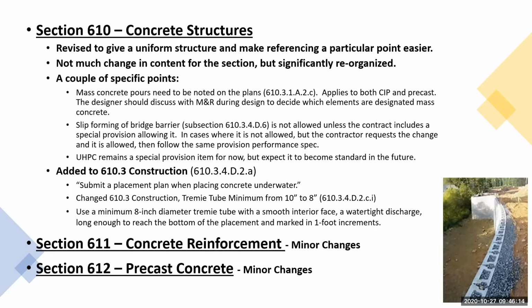Also, slip forming a bridge barrier is still not allowed unless the contract includes a special provision allowing it. In cases where it is not allowed, but the contractor requests a change and it is allowed, then follow the same provision performance spec.